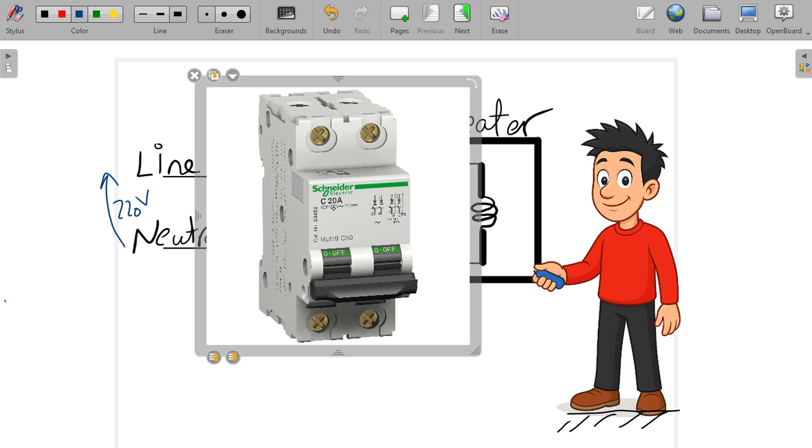When the current exceeds 20 ampere, this is considered as overcurrent and the circuit breaker will trip after a time according to tripping curve C. But let's say that the current now is 100 ampere. This means that the current is much more than the rated current, which is considered as a short circuit, and this circuit breaker will trip instantaneously.